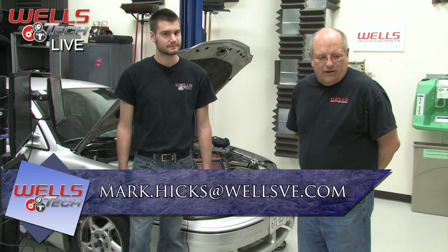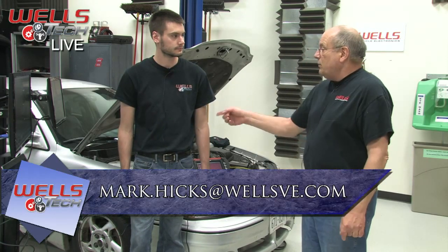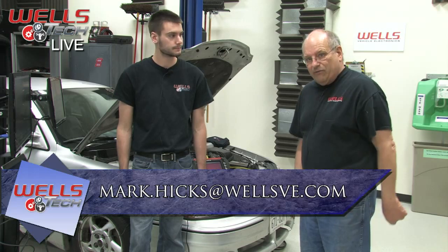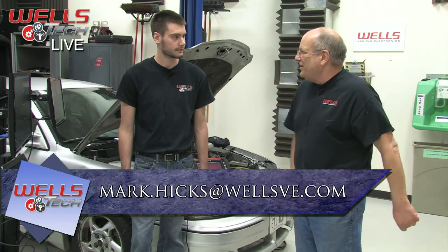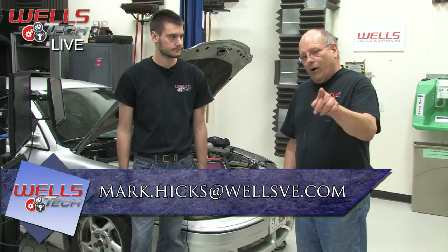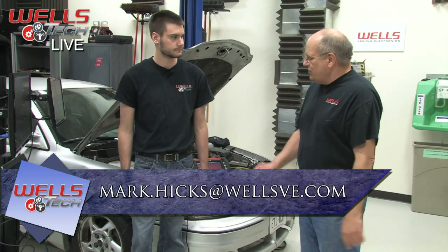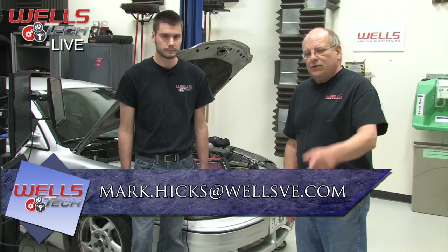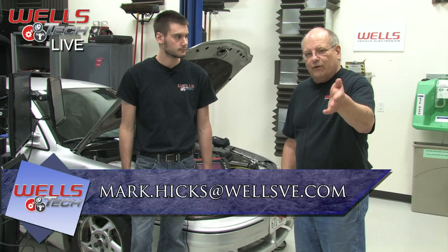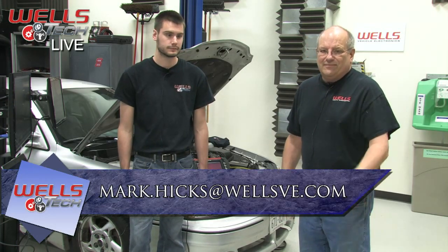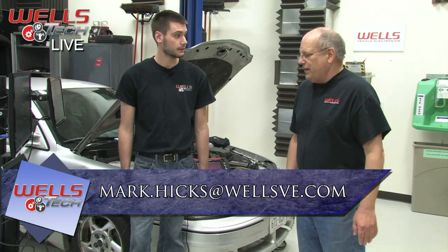All right, very good. And by the way, we're going to do a voltage drop. We're going to show you that voltage drop that confused us last time. Your homework for this week is to look at a like vehicle and see what measurement you get. See if you get 12 volts or 11 volts. We got 11 on 2 vehicles. See what you guys get. Let us know. I'd appreciate that.